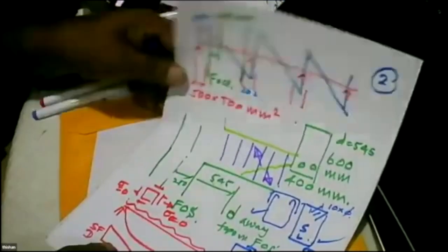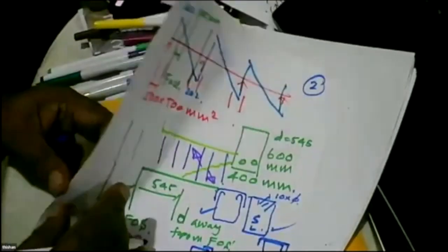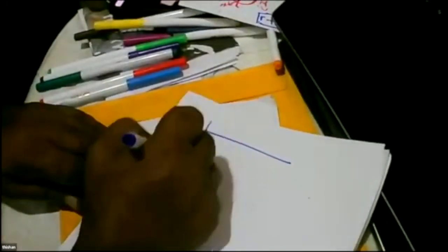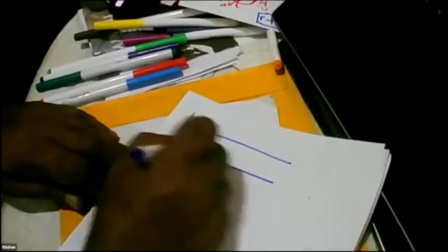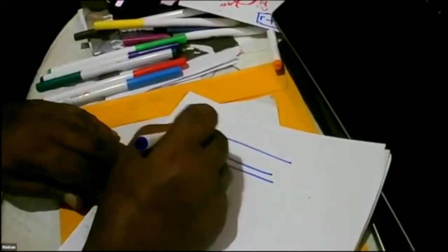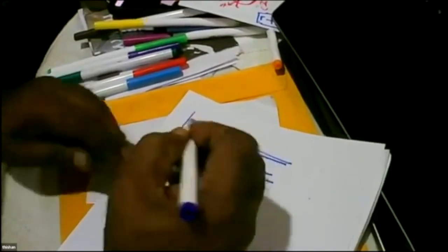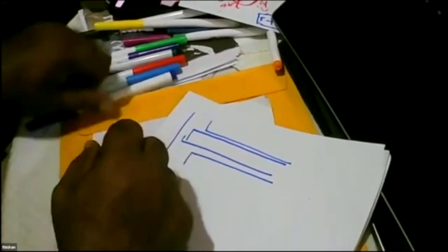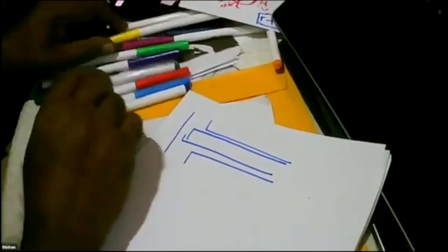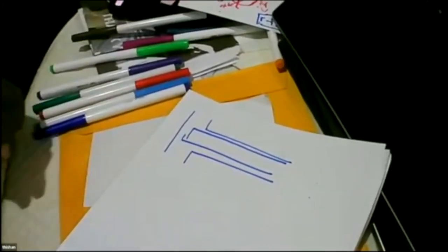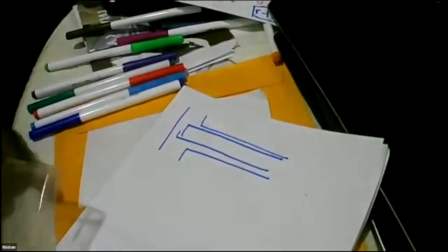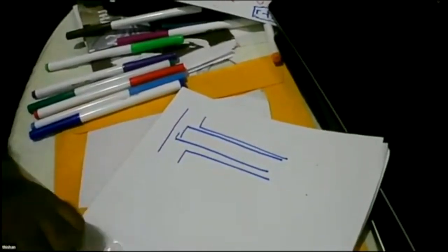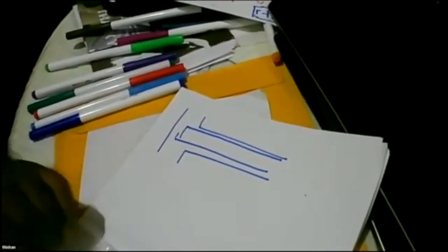So that is shear, and we know the magnitude, and we can have two types of shear. One is you have a beam with no reinforcement, just these bars, no links. Then who will carry tension? Concrete has to carry tension. How do you rank concrete? Strong in tension or weak in tension? Very weak in tension.